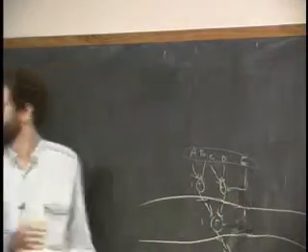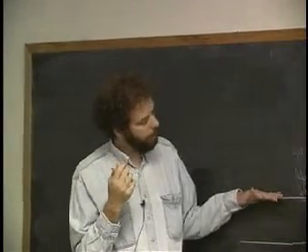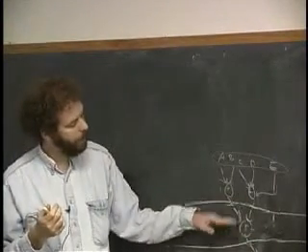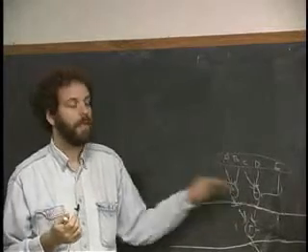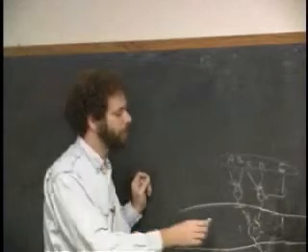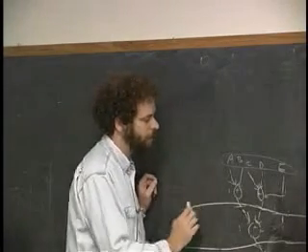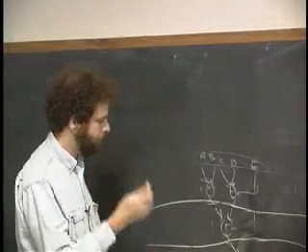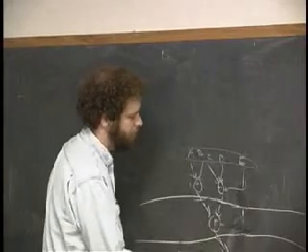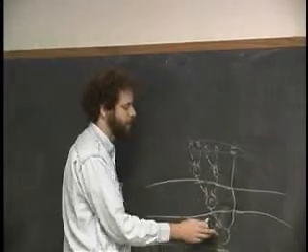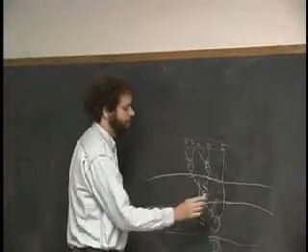Okay, good. In general, the way that you can guarantee that this is true is what we call adding the registers to the output, and then you sort of migrate them up, just as I've done here, to earlier stages in the pipeline. If you want the pipeline to perform as well as possible, let's try this in a slightly more fancy way. Let's say this element here took 2 units of time for some reason that we don't know. Okay, maybe because the numbers, by the time you add them up, get real big. So this unit here takes 2 units of time.